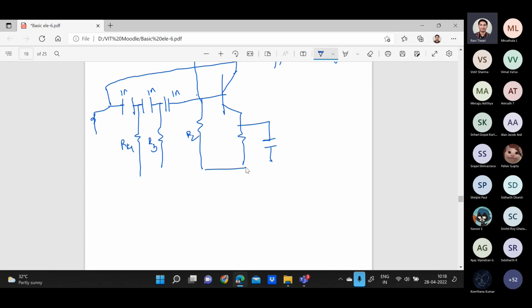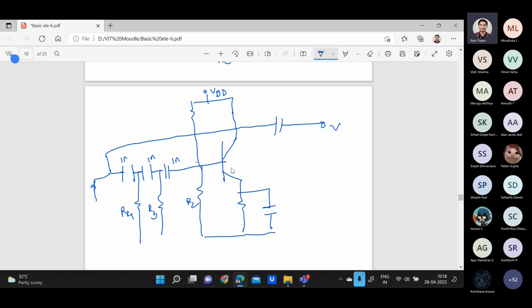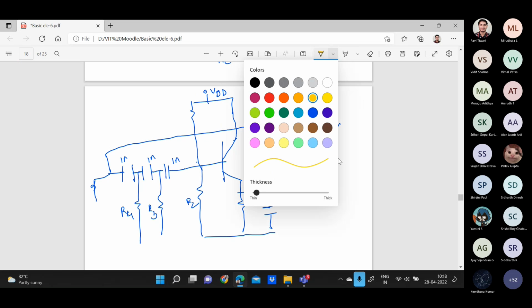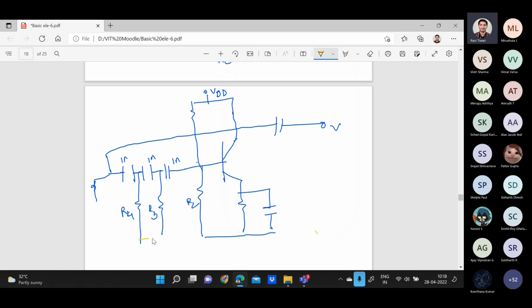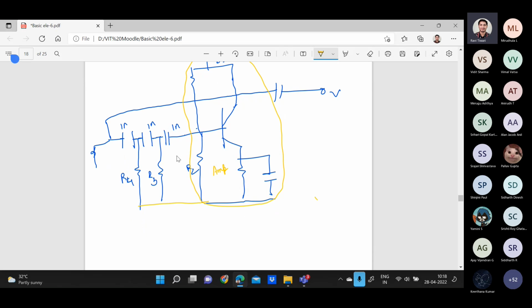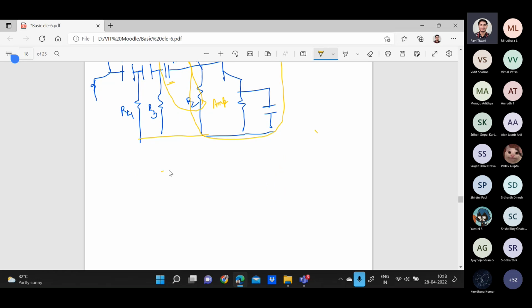And this is one amplifier circuit. All are connected, right? This is amplifier circuit. In between, you have an amplifier circuit like this. Here you can see the combination of a capacitor and resistor. One combination of capacitor and resistor can provide a 60-degree phase shift.